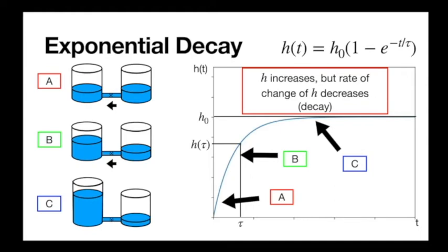You could just take it as a given that it works, but another way to think about it is just the expression e to the negative t over tau. Its maximum is 1, and its minimum is 0. At time t, if you just take e to the negative t over tau, if I plug in time equals 0, I get 1, and if I plug in time equals infinity, I get 0. So no matter what, that just decays from 1 to 0.